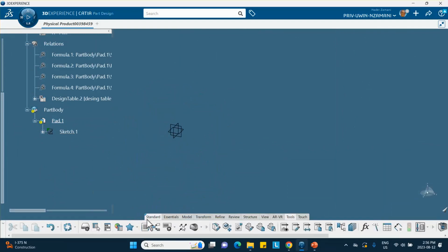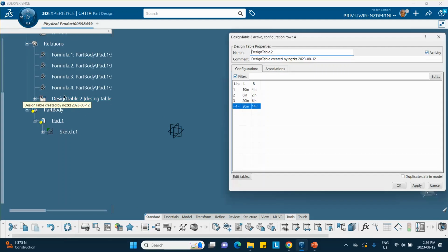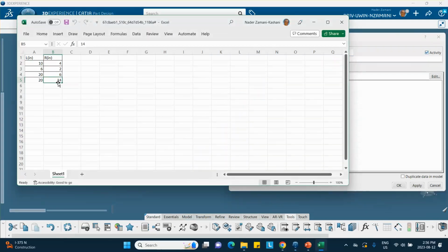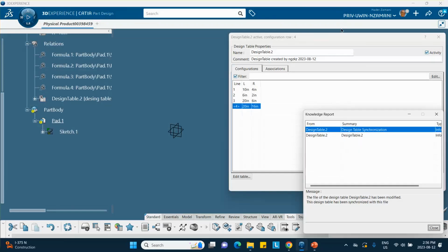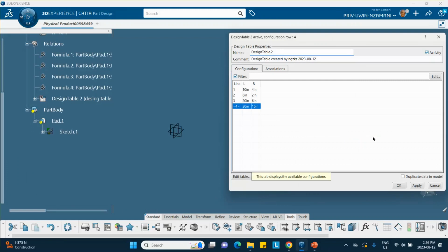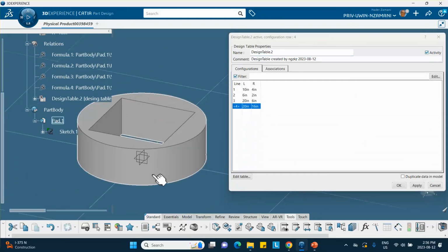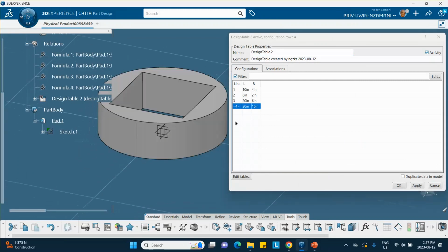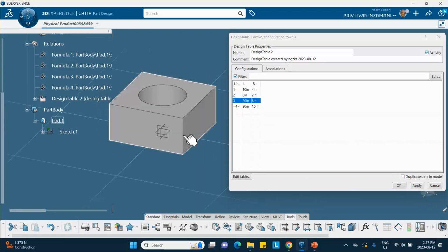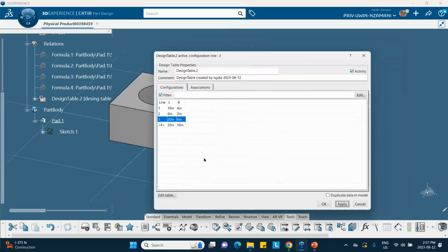Close. Okay, let's go to that table. Edit the table. Instead of 14, I make it 16 or 15, doesn't matter. You save it, you close it, you say okay, there, apply, and there we are. The other number that I put in there made it self-intersecting, but if you go to the other fellow, you're going to get back what you have.